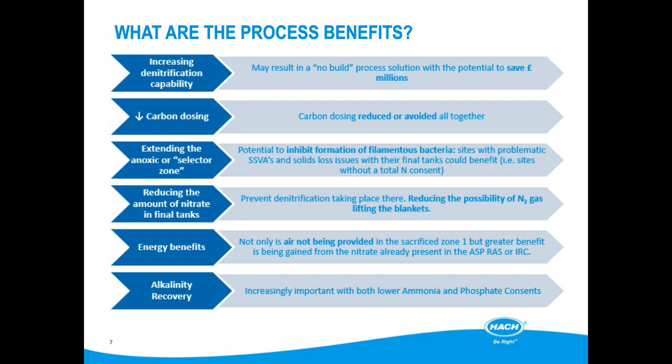Enhanced denitrification performance will lower the levels of nitrate in the final tanks. This reduces the possibility of nitrogen gassing off and potentially lifting the blankets. I appreciate this is less likely to be a problem where you already have a total N consent, but this can be an issue.